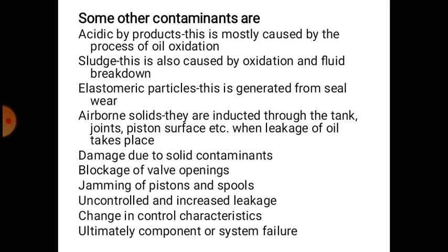Jamming of pistons and spools: the moving parts inside the valves, or it may be actuators, will not move correctly. Uncontrolled and increased leakages. There may be internal leakages due to scratches formed by the contaminants on the moving surfaces, so the oil is going to pass from one side to another side. That is known as internal leakage.